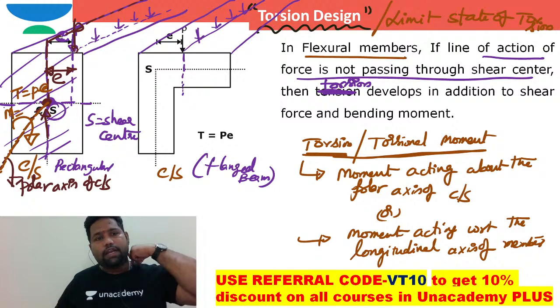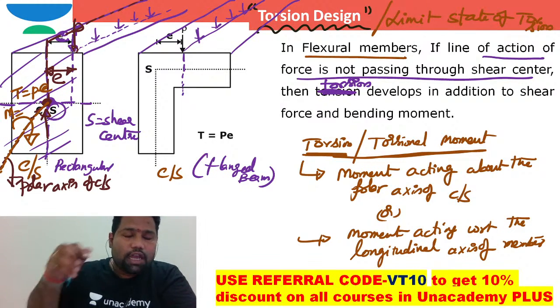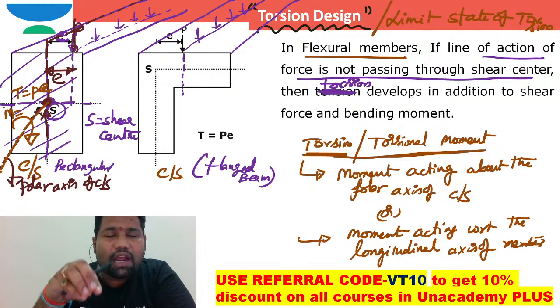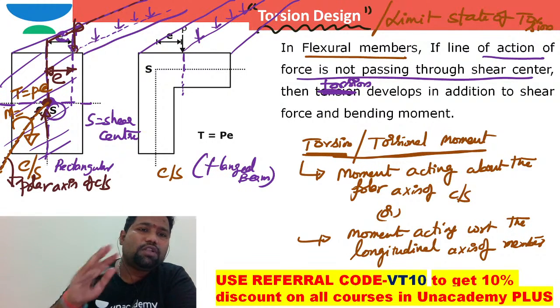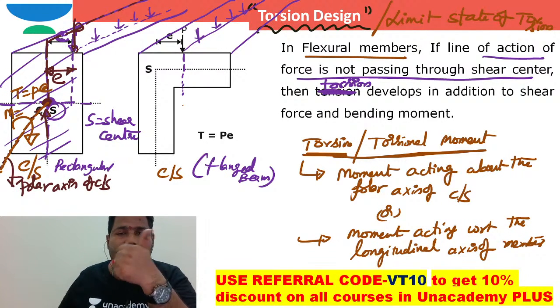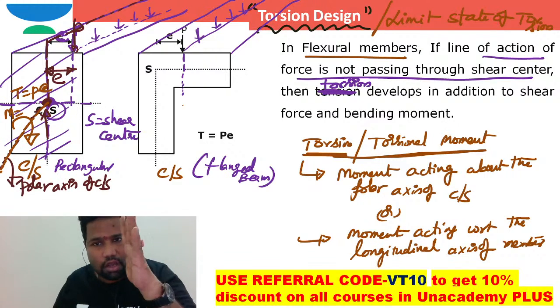So to avoid torsion, how do I need to select the cross section? Because it is a flexible plate, the applied transverse load should pass through the shear center. If it is not passing through the shear center, then definitely some torsional moment will also get developed. In such a case, for the cross section, you need to design for shear force and bending moment, and in addition you need to design for torsion also.